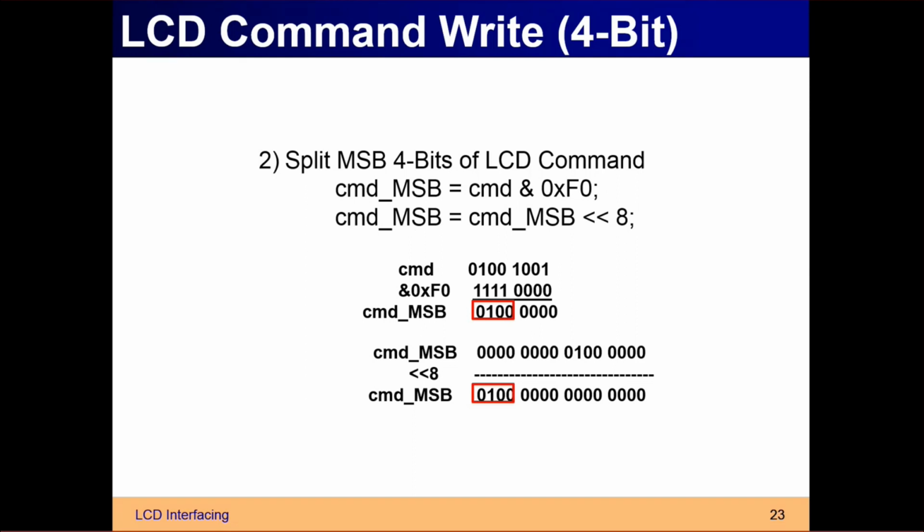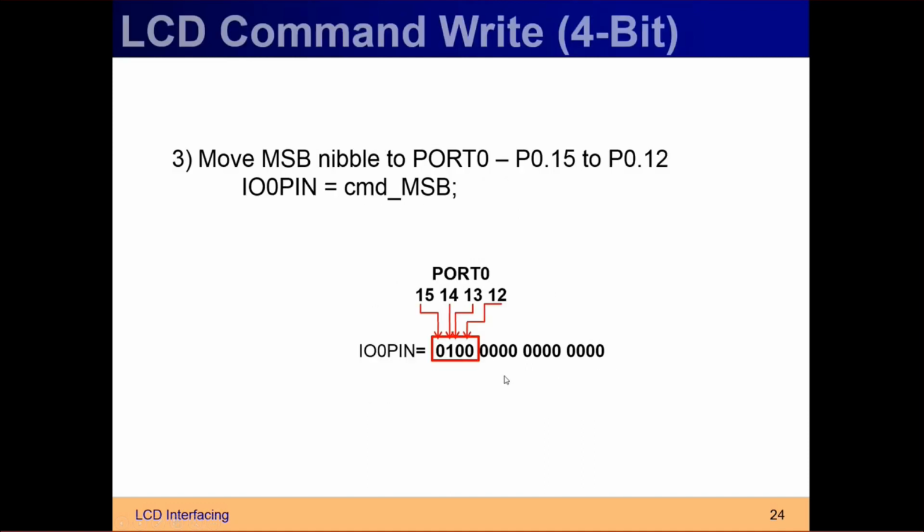So the LCD won't get the data or command, whatever you are writing. To avoid that, you are left shifting it by 8.